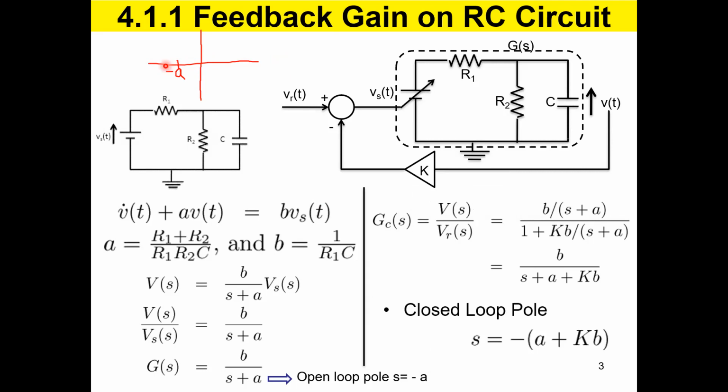Now, in all of the cases we discussed up to now, the poles were on the negative half of the S-plane. Remember the shock absorber? It has a number of different types of responses, oscillatory, whatever it is, they were all on the left-hand side.